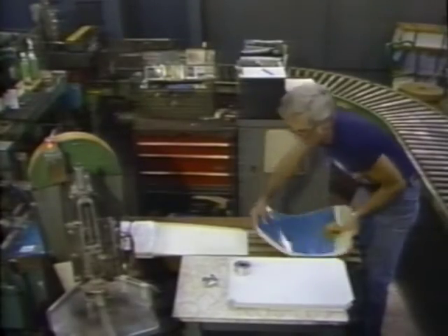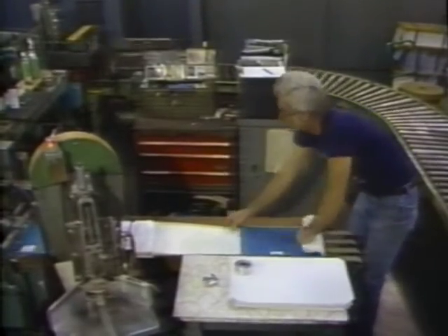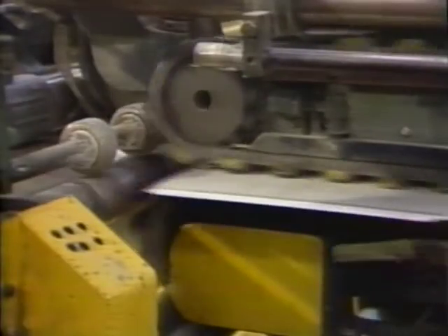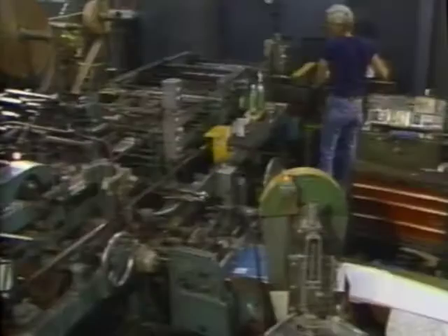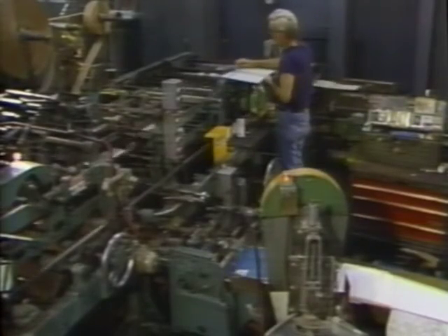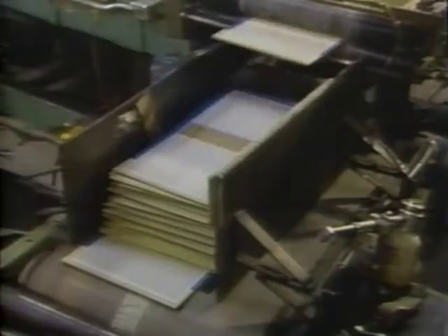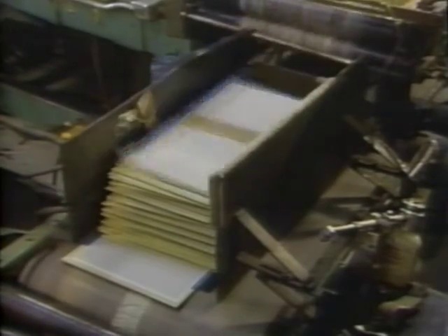The hard covers are produced as a separate production step. The back and front cover of the book is pre-printed on a single sheet of paper and then glued to a cardboard backing. It is folded to fit, and a pressure fold is put in the middle of the cardboard to form a protective spine for the pages.